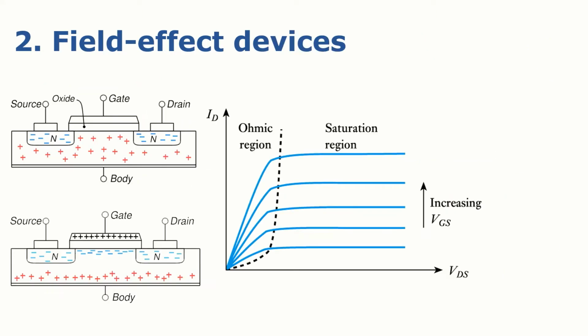On the left, we have a traditional field effect transistor with an N-type channel. Under this zero bias condition, electron transport through the channel is negligible. However, when we apply a positive gate voltage, we get accumulation of negative charge along the channel, enabling a passage for electron transport. To the right, we see a characteristic IV plot for this device, where we can check that current flux is modulated through our gate voltage.